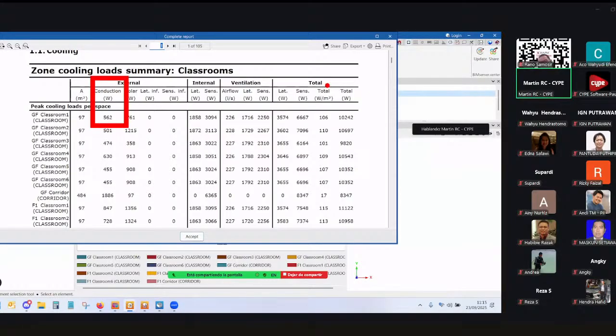So this breakdown on the consumption of power, apart from the surface itself of the area, will tell us where we are performing well or wrong. So maybe if I'm having too much solar heat gains, I should improve the behavior of that window or put just fewer windows or remove the windows. Well, I don't know, right? If my walls are losing too much heat, maybe I just put more insulation or thicker walls, whatever.